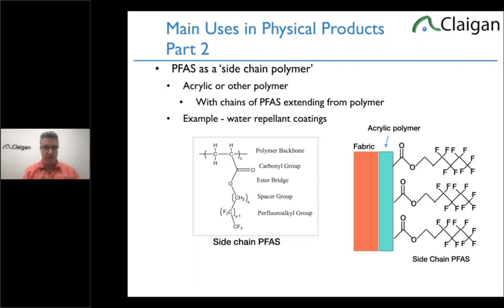The reason fluorine carbon is so water repellent is the fluorine carbon molecule has no electrostatic charge. It's got zero charge, which means water, which is extremely polar, the oxygen is extremely negative because it's pulled all the electrons from the hydrogen, and the hydrogens have lost all the electrons. They're super, super positive. So it's very much attracted to other polar substances like glass or metals. When it hits a carbon fluorine, there's no electrostatic charge and it just bounces. And that's its main use type.